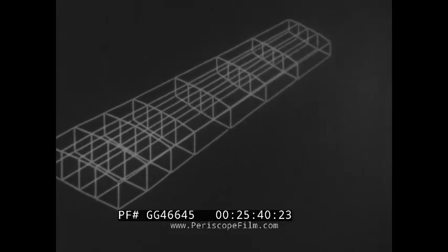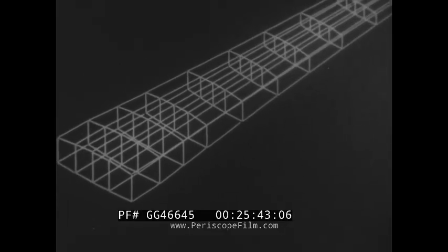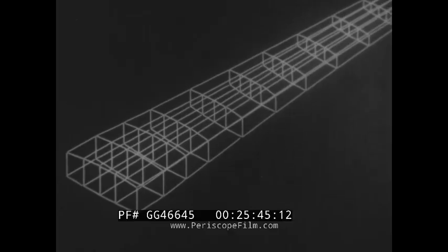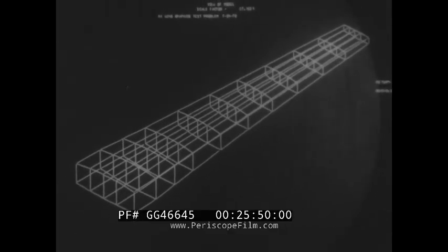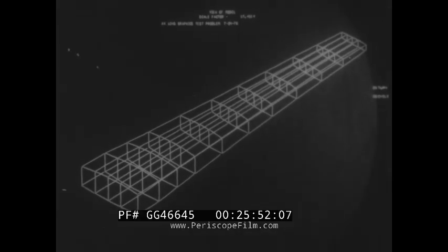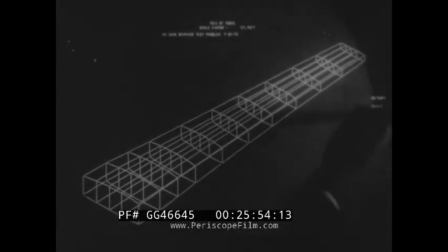From the overall view of the wing, we can locate errors in geometry and omitted members and decide which areas of the model we wish to study in detail. We now go to a display of a rib of the wing for detailed viewing and modification. As the first check, we display the shear webs of the rib. After checking the webs, they can be erased.